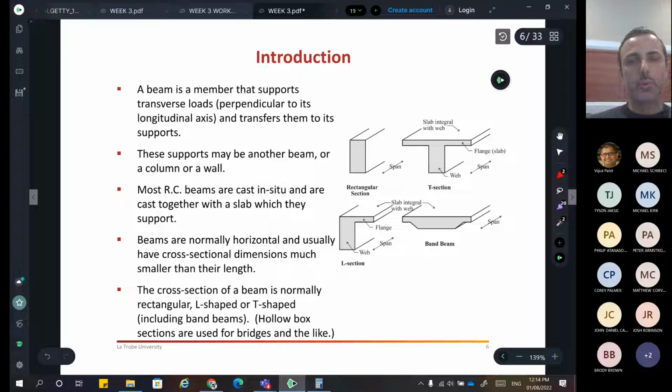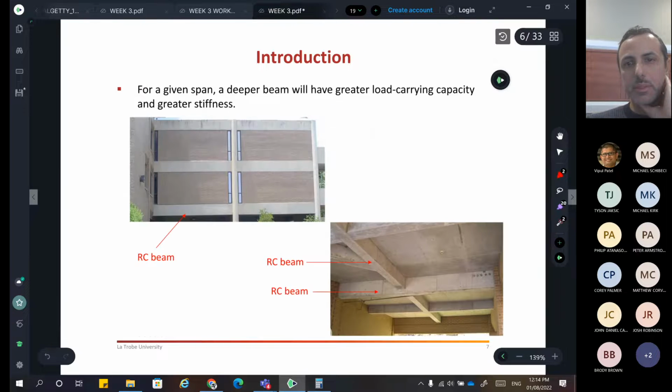They can be poured on site, and they can be poured together with the slabs, like this edge beam. Typically, they don't pour the beam and make a construction joint here and then pour the slab. They will pour the slab and the beam together. We have a picture in the following slide to understand the same thing. This is a beam, and this may be a slab running along. You see, this is the beam and this is the slab, and they're going to pour them together.